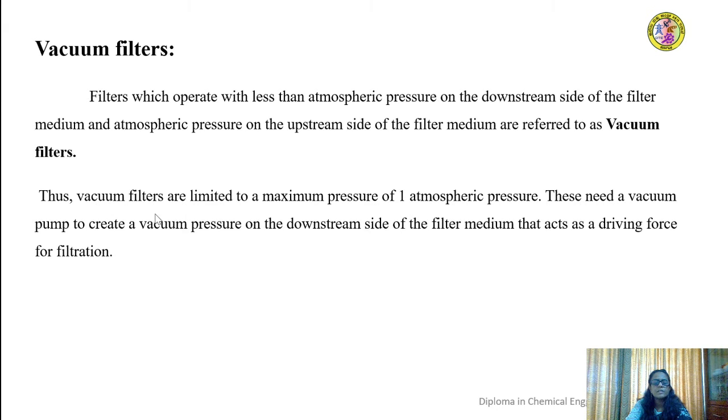So the vacuum filters are limited to a maximum of 1 atmospheric pressure. These filters need a vacuum pump to create vacuum pressure on the downstream side of the filter medium to act as a driving force. So that is an additional thing required for a vacuum filter.